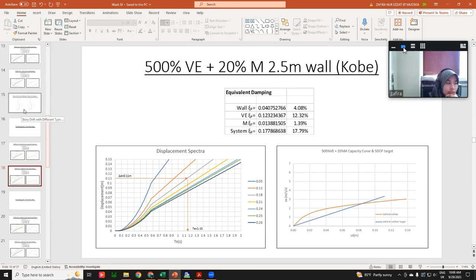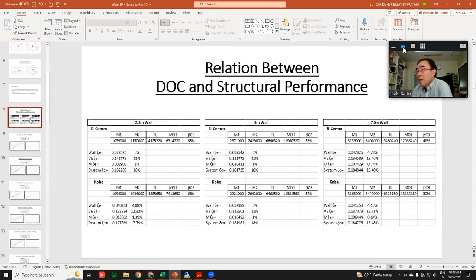Yes, Sensei. But what I understand about coupling beams is that the degree of coupling is very important. For example, different heights of story have different ranges of degree of coupling. Basically for a 10-story building, the range is between 40% and 50% or so. So the first evaluation for the building is the degree of coupling.